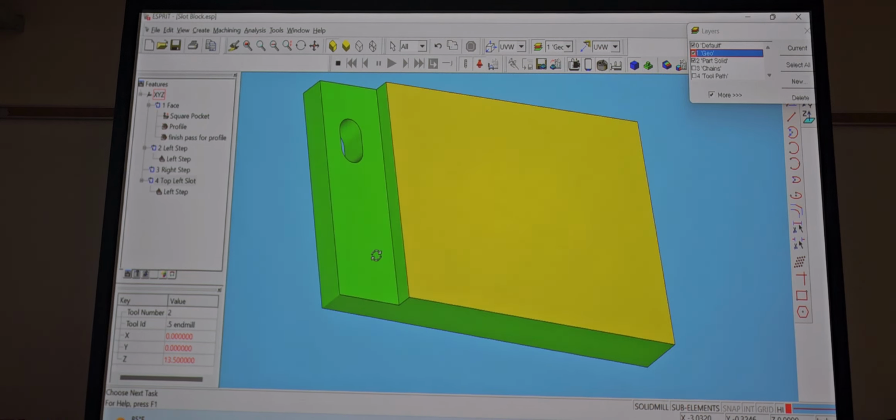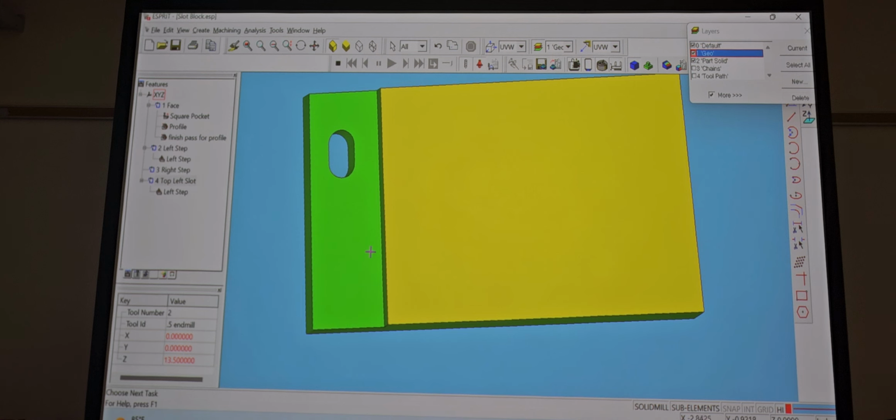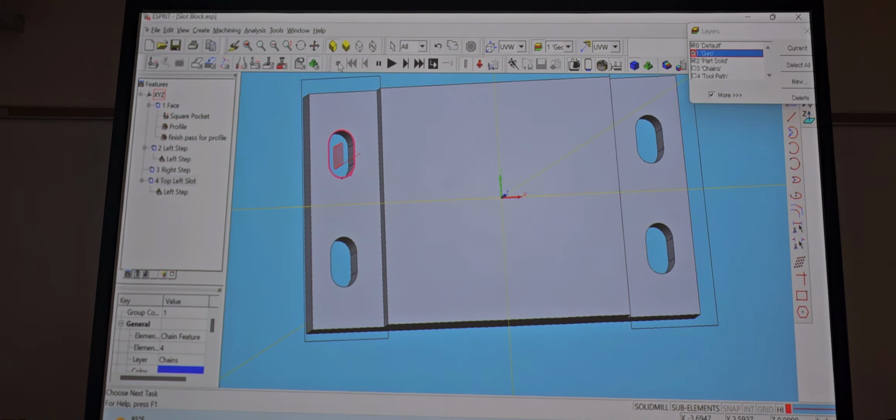Oh yeah. So now each chain that you do, it'll save that same feature, so you can just click yes, and then click on the next. If I make this pocket, it's gonna get the information from the last pocket, so you don't have to go in there and enter it every single time, as long as you don't push default off. Well, that's what we were taught.